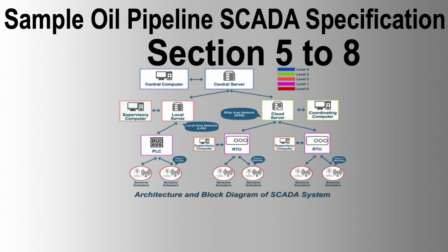6.3.3 Wiring and Termination. All wiring shall be mechanically supported within plastic non-flammable trunking with covers. Power cabling and instrument signal cabling shall be separated to avoid interference. Wire size shall be 0.8 mm minimum. Field cables and system cables shall have separate trunking or trays. Wires shall be terminated to clip-in SAK-R or equivalent knife-edge disconnect-type terminals mounted on DIN rail.